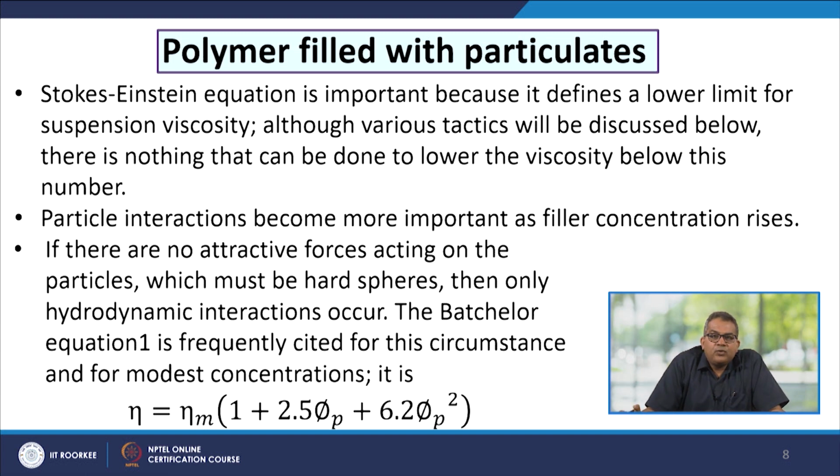Now, if there are no attractive forces acting on the particles, which must be hard spheres, then only hydrodynamic interactions occur. The Batchelor equation is frequently cited for these circumstances, and at modest concentration, it is eta is equal to eta m into 1 plus 2.5 phi p plus 6.2 phi p squared.